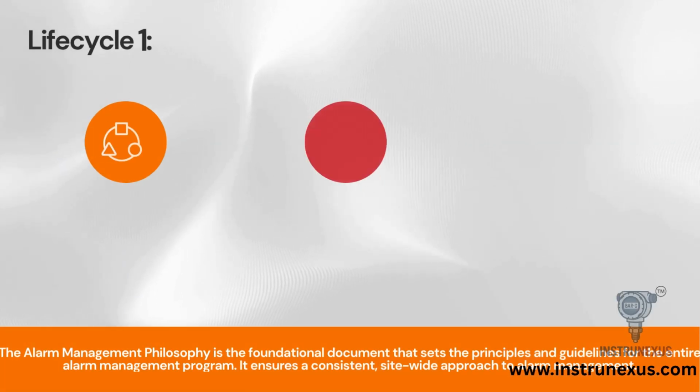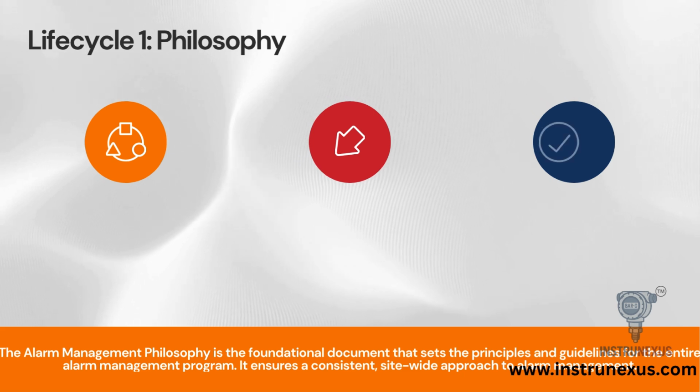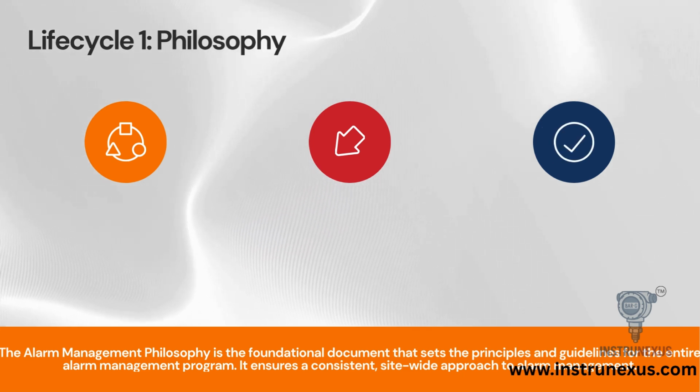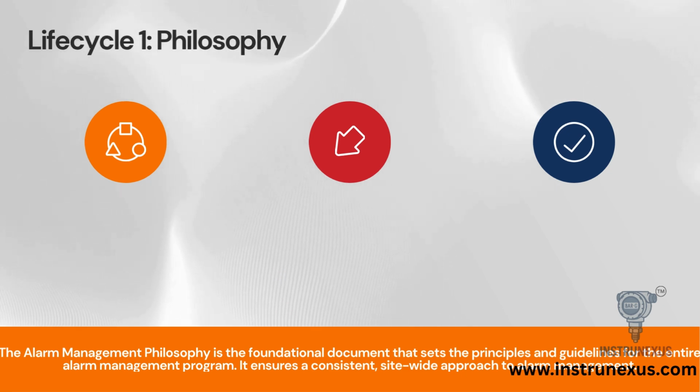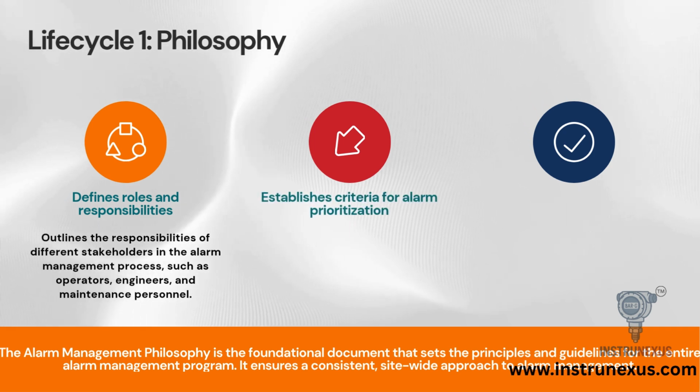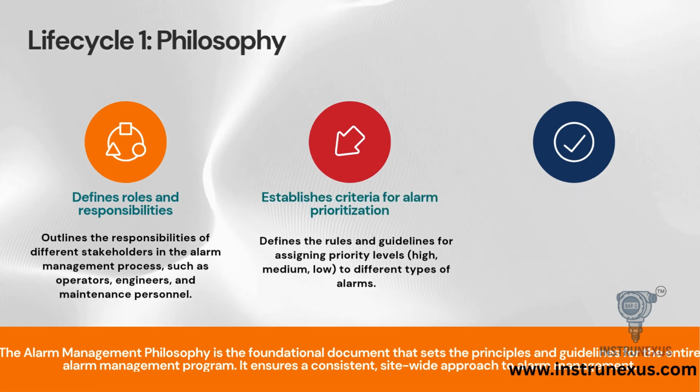Stage 1 is philosophy. This is your foundational document. Before you touch a single configuration in your control system, you must write this document. It defines roles and responsibilities. Who is allowed to change an alarm set point? Who maintains the master database? It establishes your criteria for alarm prioritization. What makes an alarm high versus low priority?